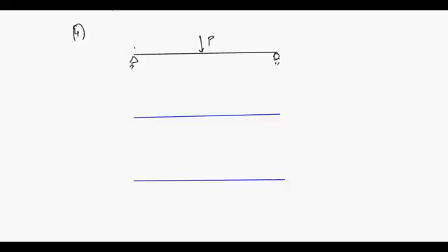Okay, so shear force diagram, if you draw, or first you calculate the reaction, this will be P by 2, you know, this will be P by 2. So this is P by 2 in upward direction, so lift this point from 0 by P by 2.